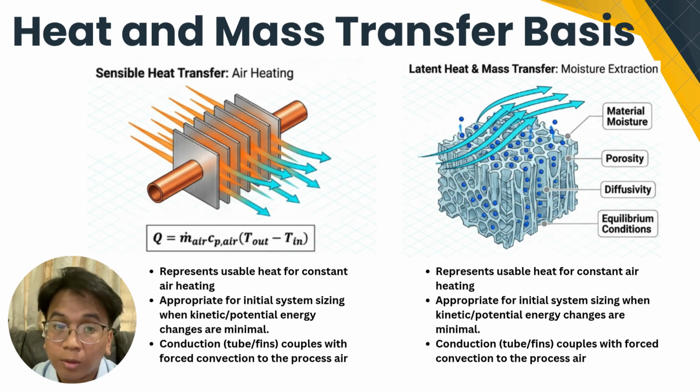However, during the actual biomass drying, heat transfer alone is not sufficient. The evaporation of moisture from biomass also involves mass transfer that depends on factors such as moisture content, porosity, diffusivity, and equilibrium moisture conditions.